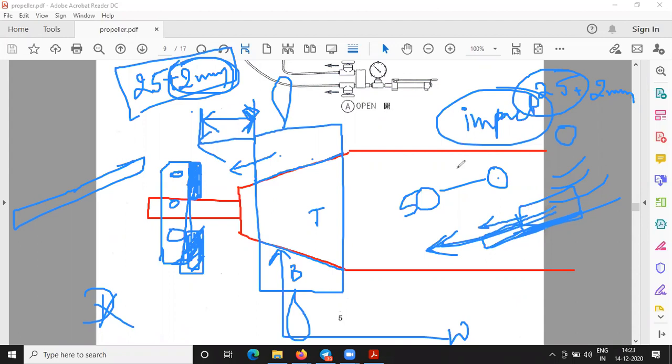Okay. Okay, sir. Clear. In the removal, we are only going to give wet pressure, but care has to be taken that for the total push-up distance plus 2 mm, you have to create a gap. That means you have to unscrew the nut and keep the cushions so that this will not come and harm the nut. So this 25 mm you have taken as the push-up distance from the standard point, right? Yes, sir, from the standard point.